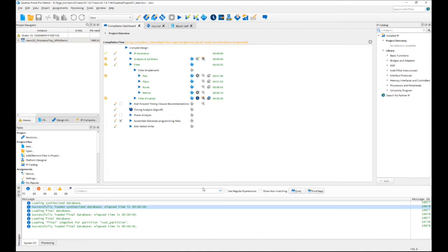So while you may have made a trivial design change, what happened was that this seed number changed. The tool started looking for a solution to your problem in a different spot in the FPGA, and the tools ran with that. Sometimes what happens, and it's unfortunate, but that's the nature of the game, is that what was passing timing before is no longer passing timing, and it's because of this.